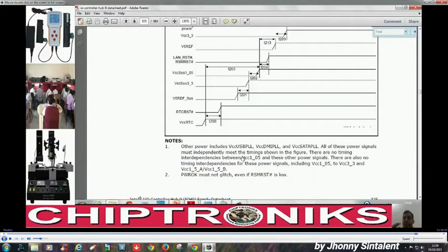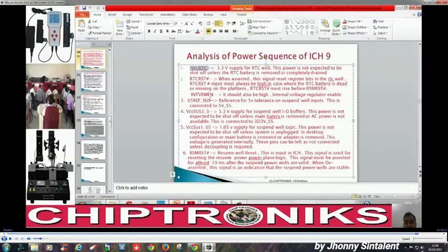If you follow this procedure, you see how, checking VCC RTC, we go back to check the 3 volt 5 volt regulator, right? So now my second is RTC reset hash. First we'll understand the meaning of this signal. RTC reset hash, when asserted, resets register bits in the RTC well, and the RTC reset input must always be high.